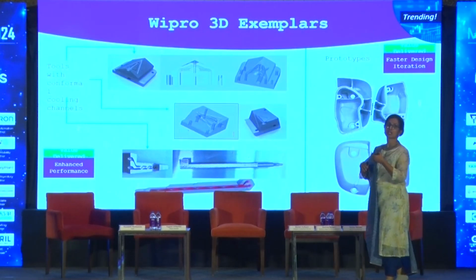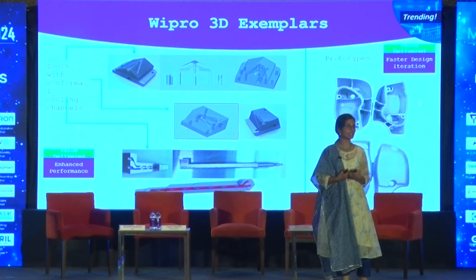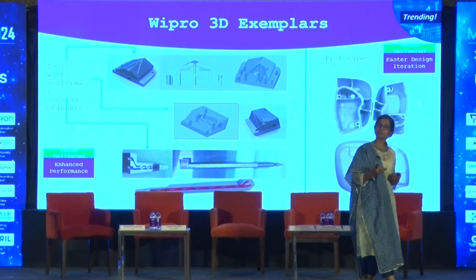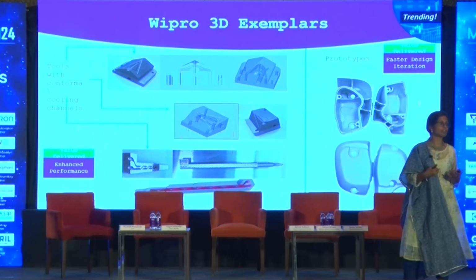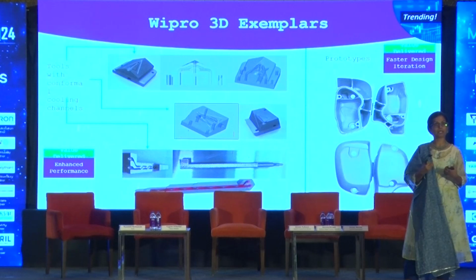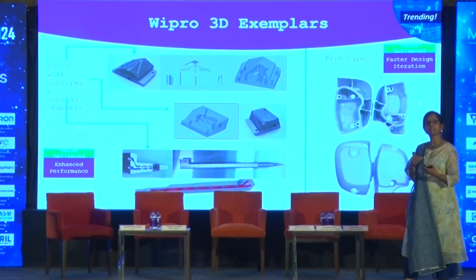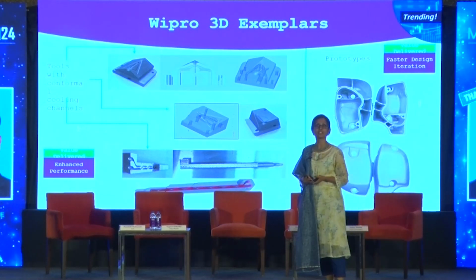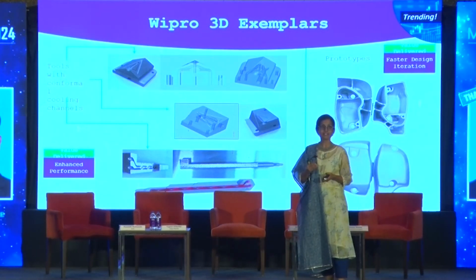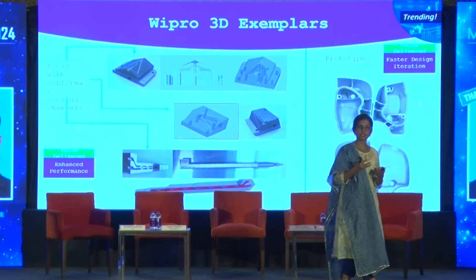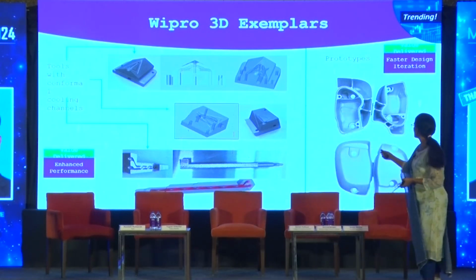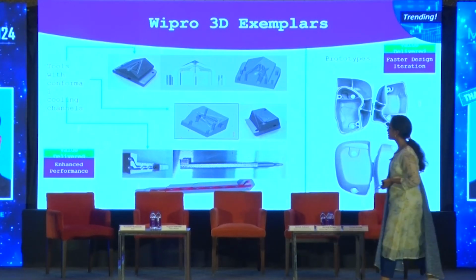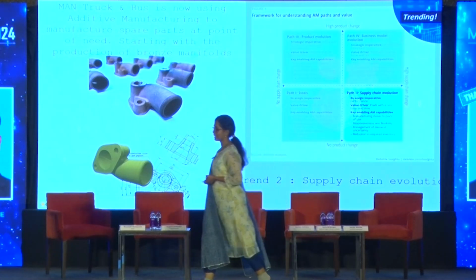Tools used for, let's say, injection molding or die molding are very popular. We have one particular material called maraging steel. We call it MS1, a very hard material. When you make tools with that using additive, you have the advantage of making complicated cooling channels which are conformal. Hence, you can make more parts per minute because your tools are getting cooled faster. So some examples of that, but also some examples of the prototypes that you see here. So this is part number 1, status is done.